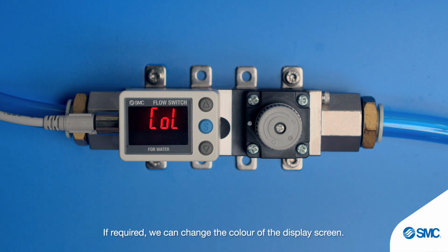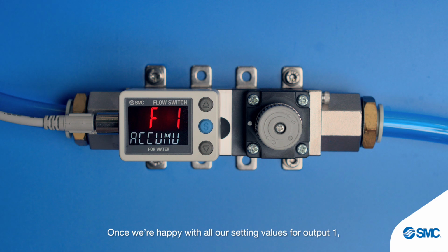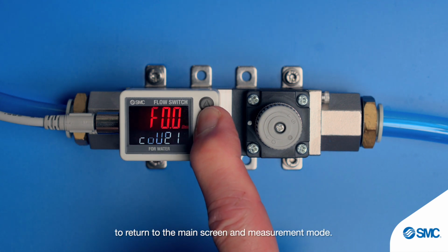If required, we can change the color of the display screen. In this example, we're leaving the setting to provide a green display screen when output 1 is on. Press the set button to accept. Once we're happy with all our setting values for output 1, press and hold the set button for more than 2 seconds to return to the main screen and measurement mode.